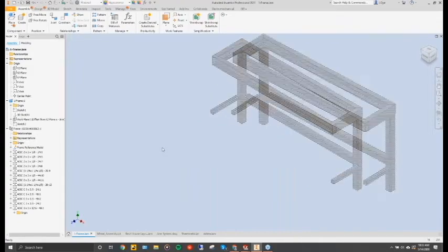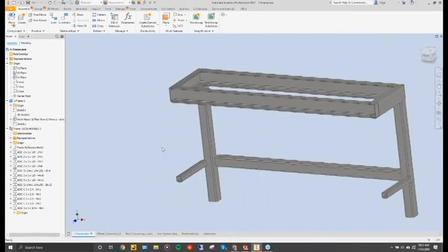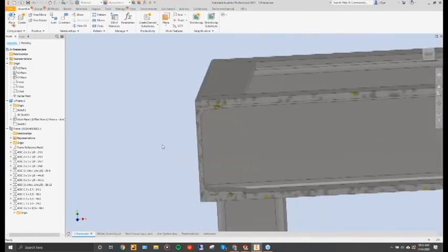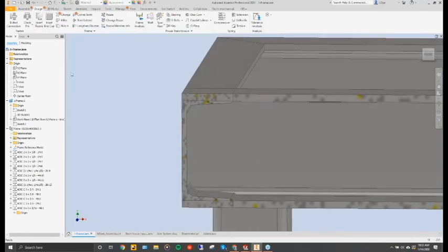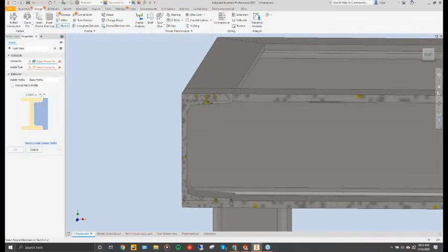All right, so getting into the frame generator. Let's do this one here first. I'm just going to bring up design here, and then I can click on that notch. See the new layout of the dialog box here. You have your basic profile, custom, I template, C template, and T template. I'll just leave it on basic profile for right now.